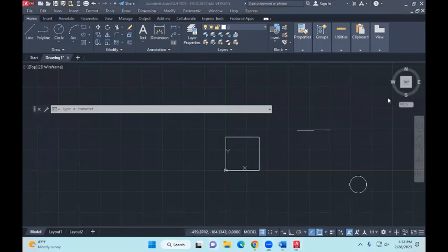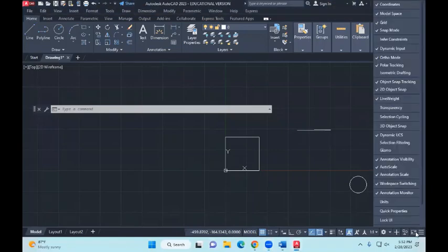So that option is called what? How do I move this? Okay. So you go right at the bottom right corner, there are 3 horizontal lines you'll see. Click on it. It says customization. Click on it. Okay. And you'll see dynamic input. Make sure it's checked. Make sure there's a tick beside dynamic input. Right. Set. So it's checked. Now you go and turn it off.